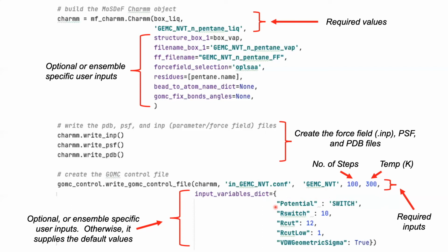Now, all of these are typically set as standard default, except in the case, I believe, of the grand canonical ensemble, where you have to select a dictionary with a residue and a chemical potential or a fugacity, which just can't be set automatically because it's very specific.